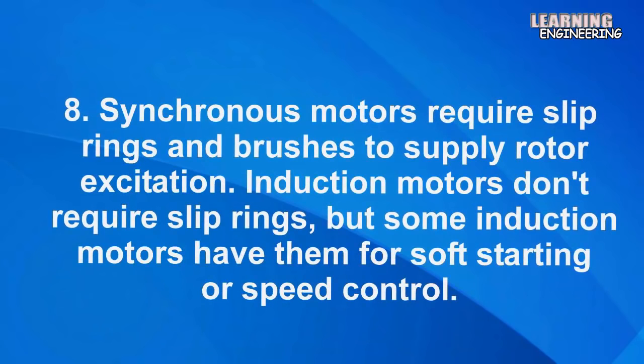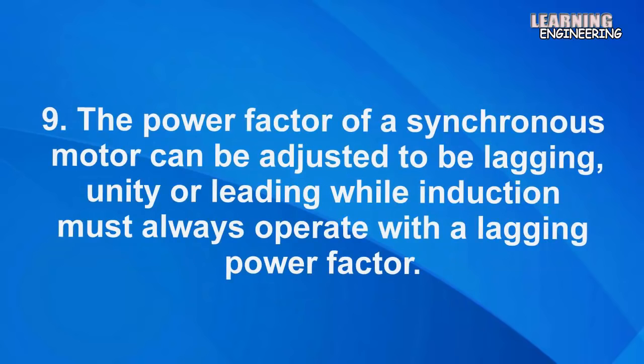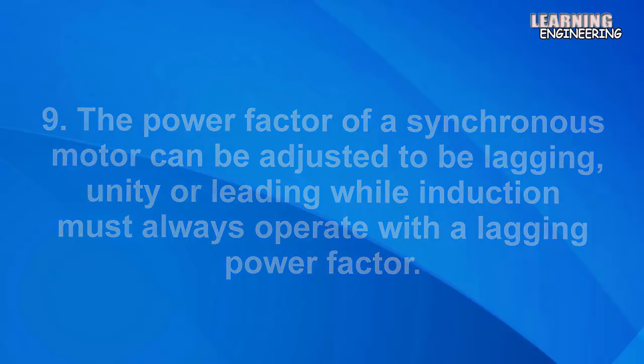8. Synchronous motors require slip rings and brushes to supply rotor excitation. Induction motors don't require slip rings, but some induction motors have them for soft starting or speed control. 9. The power factor of a synchronous motor can be adjusted to be lagging, unity or leading, while induction motors must always operate with a lagging power factor.